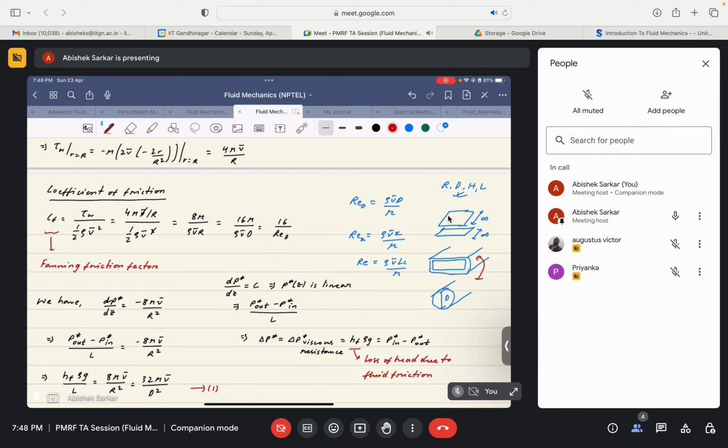So in some way we can say these flows are similar, but physically the formulas that we obtain for solving flow through pipes would be completely different from those for flow through rectangular ducts. In these kinds of geometries we define an equivalent diameter or equivalent length scale to define the Reynolds number. Could anyone tell me what that diameter is called? Equivalent diameter is called? Hydraulic diameter, sir. Yes. That is given by 4 times the area of the confinement divided by the wetted perimeter.